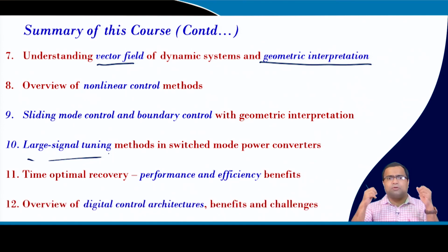Then we also discussed an overview of some digital control architecture. Since this course is not for digital, but I have given some insight that whatever we learn, some of this can be implemented in digital control, and some of the modulation techniques that I have taught in this course, like regular trailing edge pulse width modulation, then constant on time, constant off time, as well as hysteresis control, can be very effectively implemented using a digital platform with small resources, and they are useful for high frequency applications.